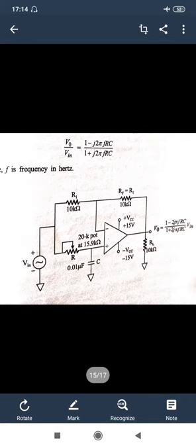Here we take the gain, which depends on the values of RF and R1 after designing. According to the resistance values we have chosen, we have taken the gain of this circuit. According to this graph, in the mid frequency range the gain is nearly equal to the maximum, and at the lower and higher cutoff frequencies, FL and FH, it decreases by a factor of 1.414.